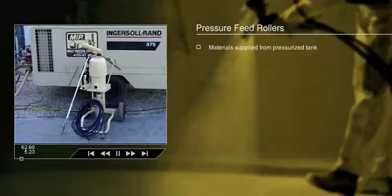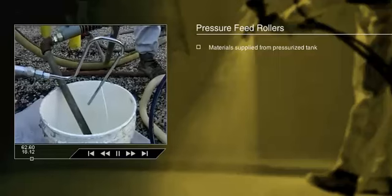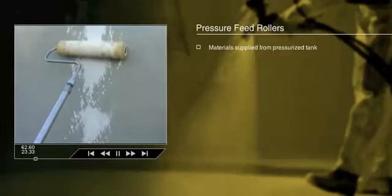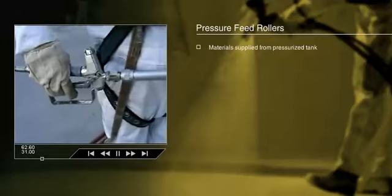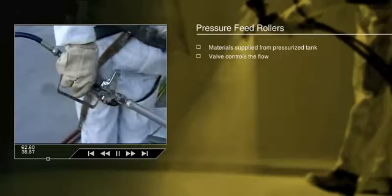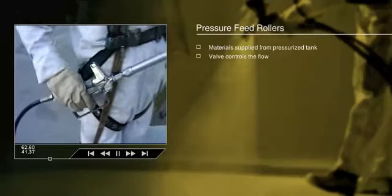Pressure feed rollers allow for application of a continuous coating film by supplying materials from a pressurized tank directly into the roller. The roller core is made with a perforated metal case that allows the coating to flow from inside the roller to the outer surface of the roller, where it is readily available for application. A valve on the handle or the tank controls the fluid pressure and moderates the flow of coating to the roller surface.